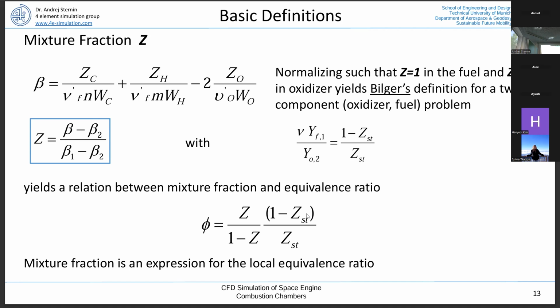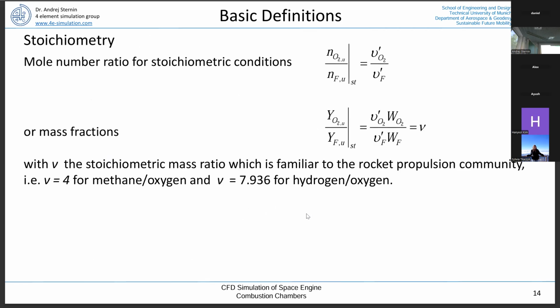Combustion temperatures would be small, and NOx formation will also increase the molecular weight. And since we are riding on the exhaust jets, the molecular weight of the exhaust jet basically defines the exit velocity: the higher the molecular weight of the exhaust gas, the lower the jet velocity. And riding on the jet means we have to have the lowest possible molecular weight of the exhaust gas. So that's the reason why we don't do that.